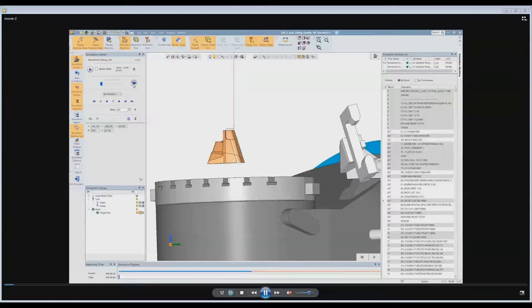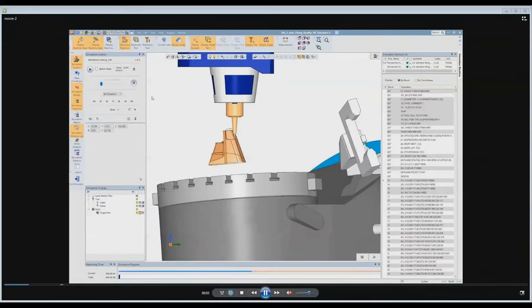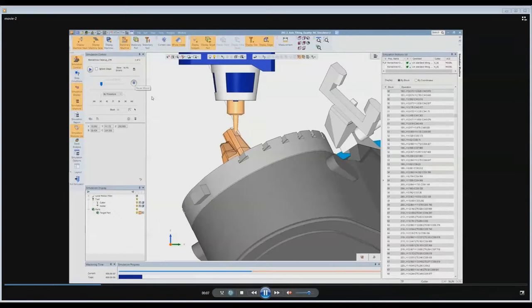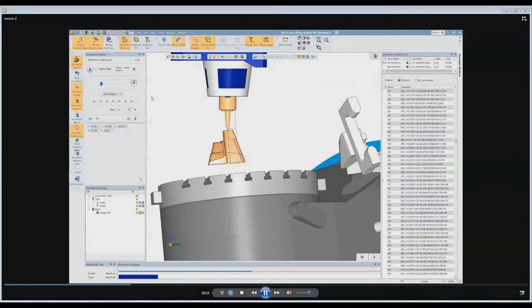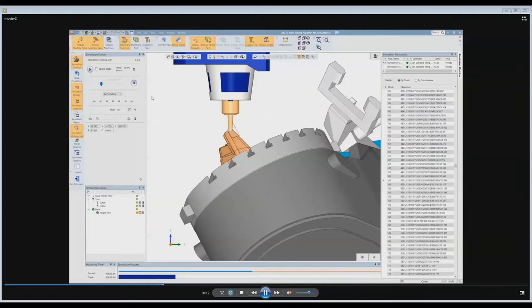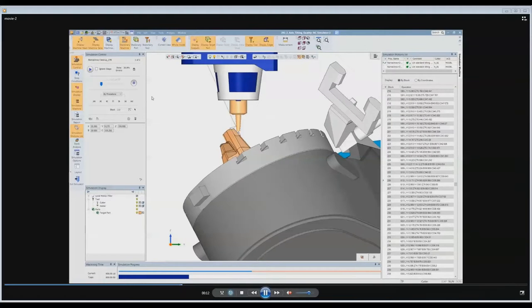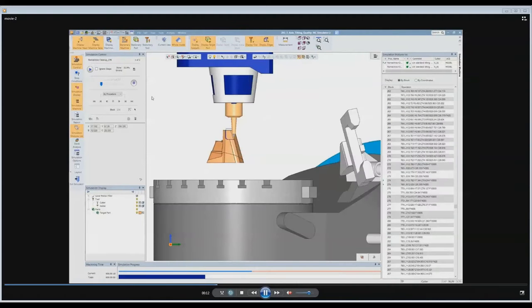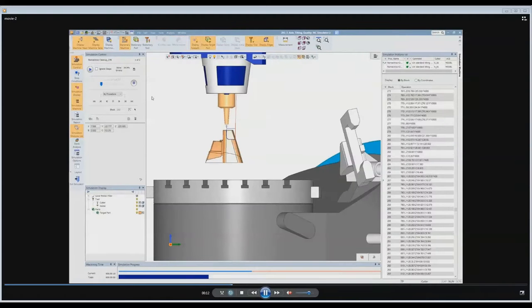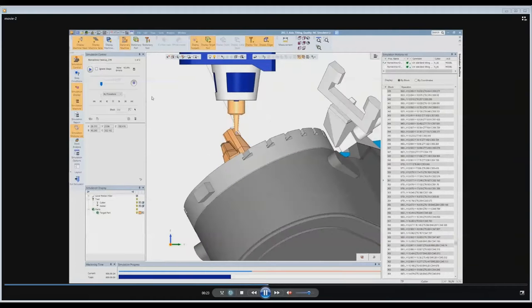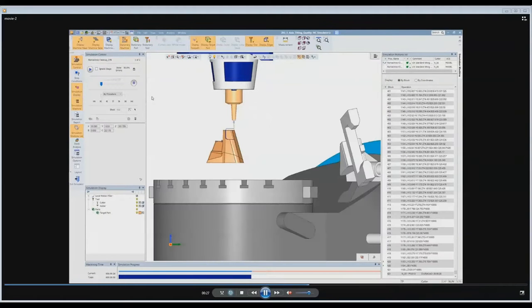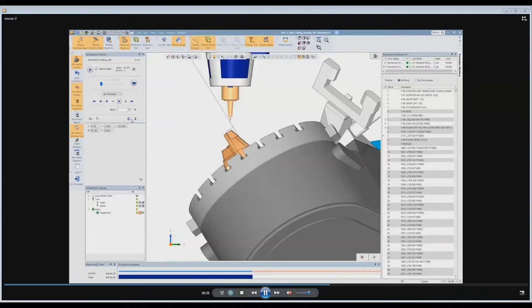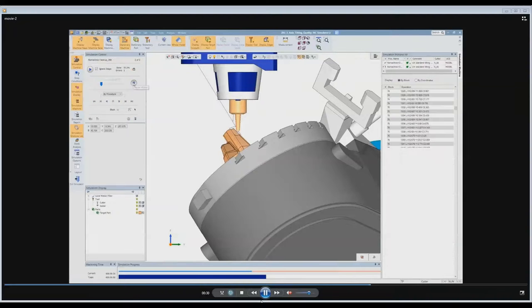So first we are seeing the table is being rotated only when the holder is close to the job, and when the holder is away from the job, the table is rotating back. So this motion of back and forth causes backlash and may cause different axis unnecessary motions. They will not cause any gouges, but they will cause bad surface quality.